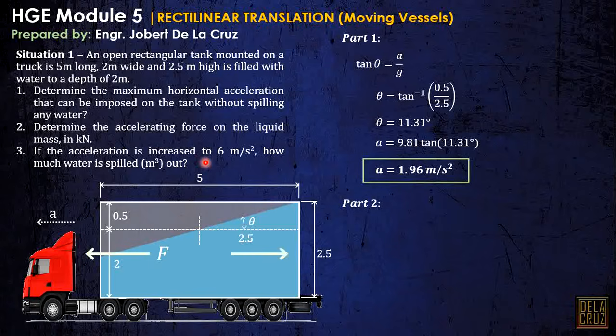we have a formula, right? By drawing the free body diagram, this is what we will use to find the accelerating force. Right? Our movement is toward the left. Then, how do we get that accelerating force, the F? We equate it to the reverse effective force. That is our concept. No, that is an imaginary force, the unbalanced force there.